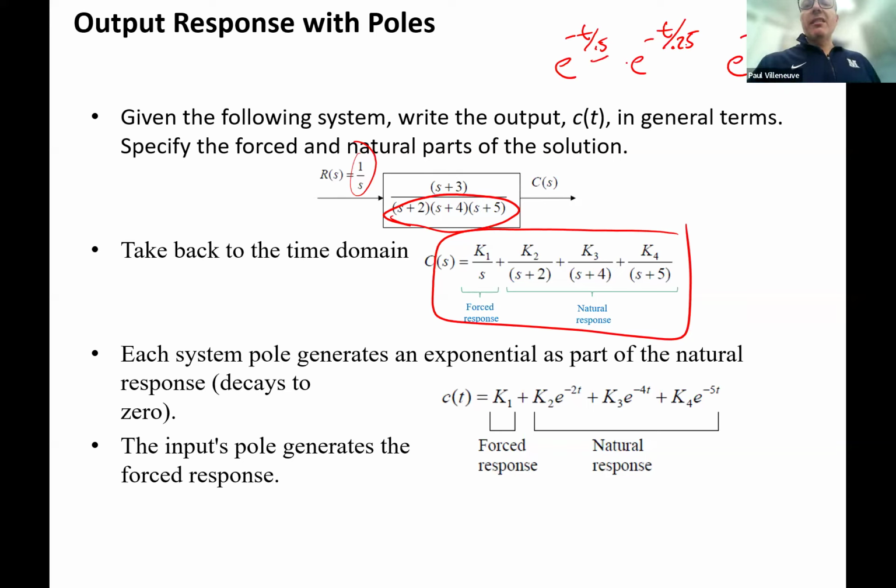And these numbers here are all taus. So the question is, how many time constants does the system take before it reaches steady state? Generally we say about 5 time constants. So if I look over here, 5 tau 1 is greater than 5 tau 2, which is greater than 5 tau 3. 5 times 0.2 is 1. 5 times 0.25 is 1.25.